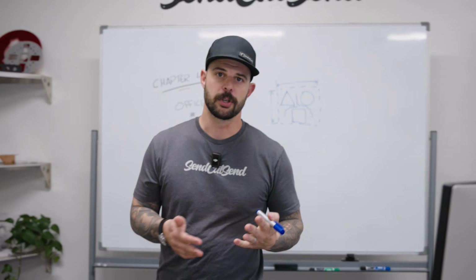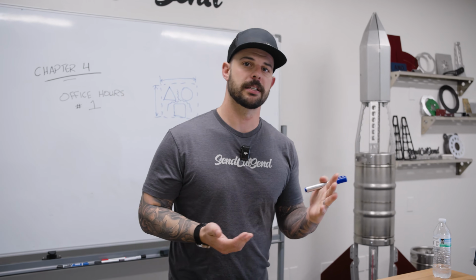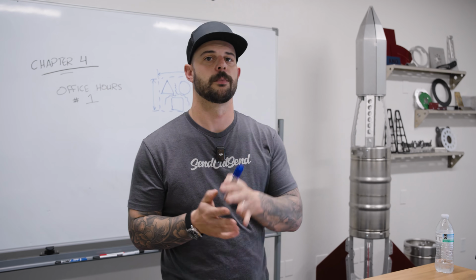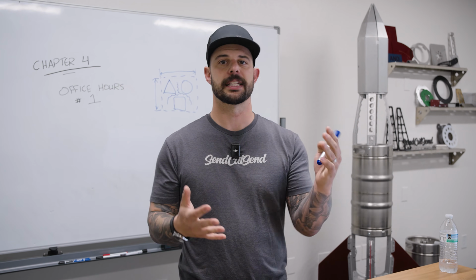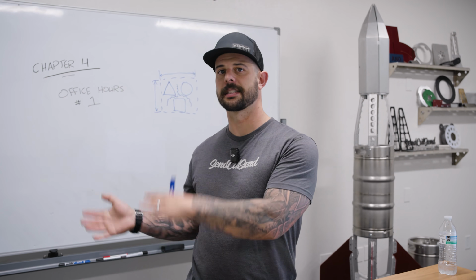Now coming over to the computer, we're going to go into Fusion to show this. There's two different ways in which we can pull that DXF in. We can go to File, Open, and then select that DXF. However, that's going to put us into a sketch DXF mode, and we're not going to be able to get individual components out of that as easily.